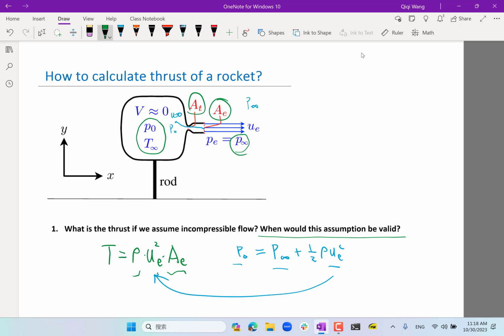Well, actually, if you just want the Mach number to be much less than 1, you can get by assuming everything is incompressible and calculate the velocity over here, by basically backing out, if you have UE, then in incompressible settings, UE times AE divided by AT would be the velocity over here, right? And if that velocity, assuming the speed of sound is constant, which can be calculated from here, is very small, you can say, okay, it's incompressible. So let's get to the compressible question.